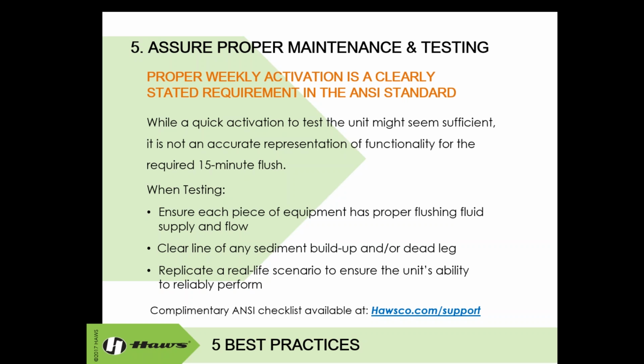Length would be determined on how long your piping may be. So if you've got an extremely long loop, flush that long enough to make sure all of that water that could be sitting in the piping and exposed to hot temperatures is all cleared out, and any sediment buildup that we don't want getting into the face, eyes, or body is cleared out.